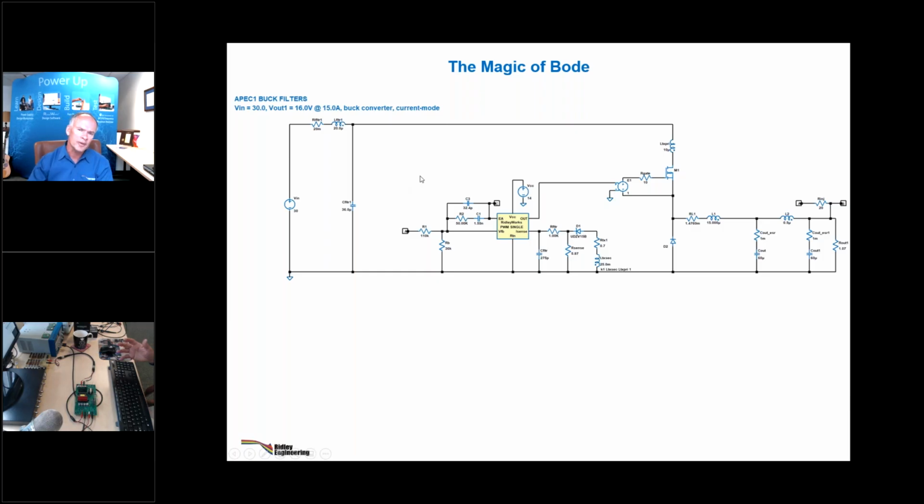So my fifth order switching converter is now, depending on how you look at the analysis, a sixth or seventh order circuit. And then lots of people, of course, get noise on the output, so a little post filter goes here, and now you've got an eighth, ninth order circuit. So 8 state variables if we don't include the sampling of current mode control. So we've got an 8th order system to deal with.